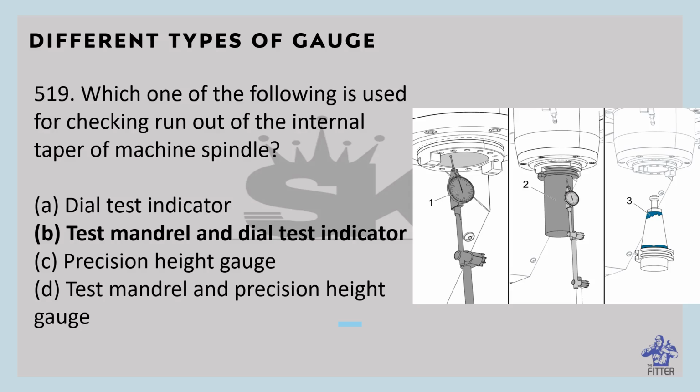Both dial and test indicators are mainly comparative devices. Test indicators accelerate consistency measurements as opposed to comparative ones. They are most often used to explore relatively broad part surfaces in either one or two dimensions, for example, measuring variation in height, flatness, and roundness. They are designed to measure in vertical and horizontal positions and are typically used to measure clearances, tolerances, and variation in tolerances of machine parts to ensure accuracy.